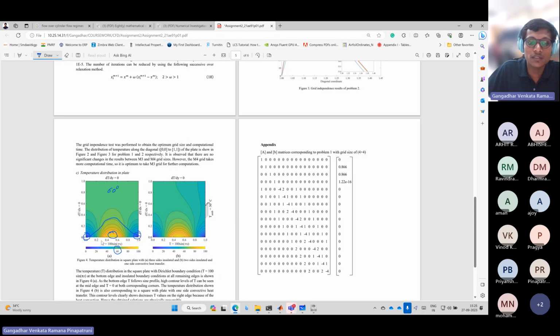Even though you are heating the slab by maintaining a constant temperature at one end and insulating all other ends, and the maximum temperature in the slab is 100 degrees Celsius, the final temperature in the entire slab is only 60 degrees at all the other portions. It is not necessary that all parts will be continuously heated to completely become 100, because here you have a heat source, and you also have a heat sink, since it maintains 0 degrees Celsius at both corners because of the boundary conditions we gave. Clearly try to understand this. You are heating with 100 degrees Celsius here.